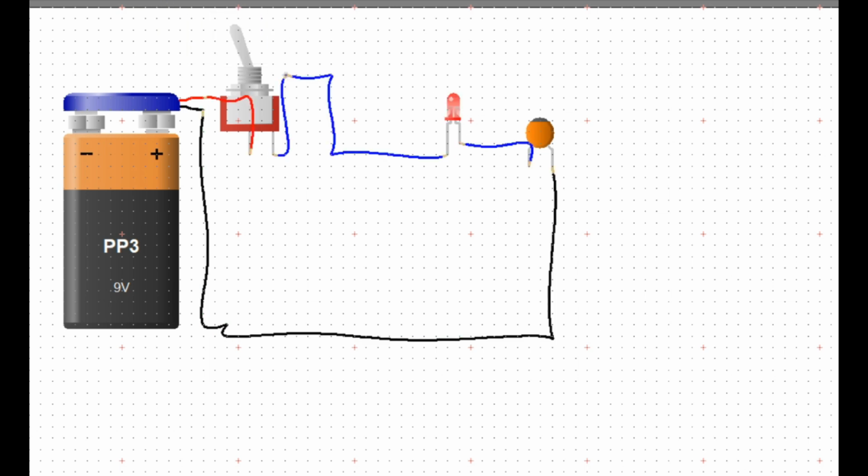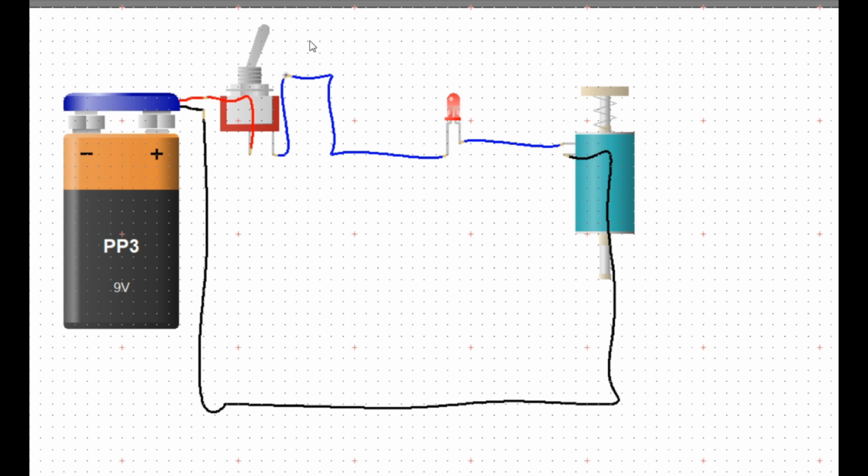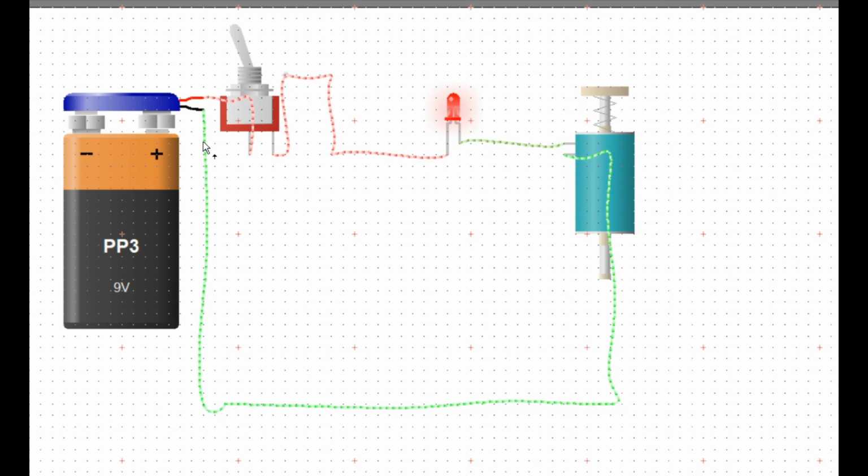Why? 1. Initially, the inductor resists the change in current, but once the current stabilizes, it acts like a regular wire. 2. Since the inductor doesn't block DC current, the current flows through the circuit, powering the LED. 3. The LED glows because it receives the necessary current to emit light. In a DC circuit, an inductor behaves like a short circuit, a wire with no resistance once the current stabilizes. This allows the LED to glow.